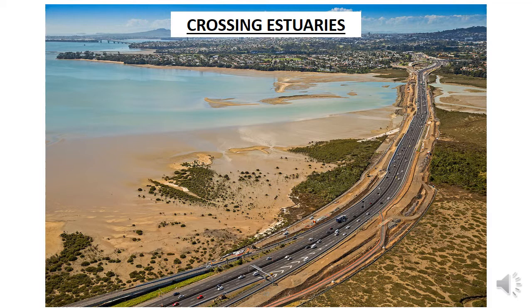The road runs on an embankment which is constructed in a tidal estuary area. The designers had to consider the sea levels for all tidal conditions, as well as allowing for sea level rise due to climate change. In addition, they also had to consider that the estuarine muds upon which the road was built were very soft and would settle over time, so they had to add an allowance for that level reduction as well. When the water body gets too deep, then earthworks may no longer be feasible and we need to build bridges or causeways to carry the road. These structures are not part of this course.